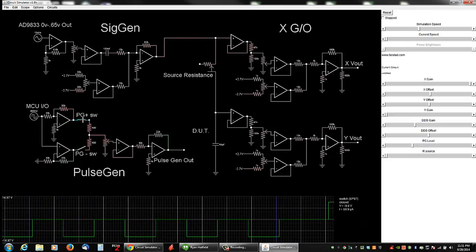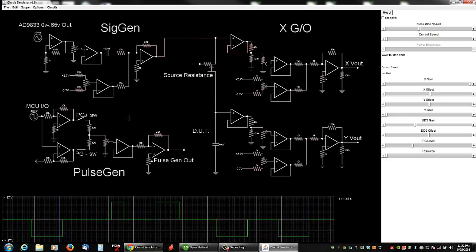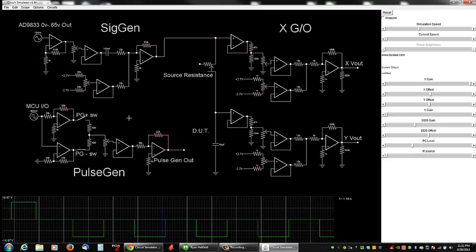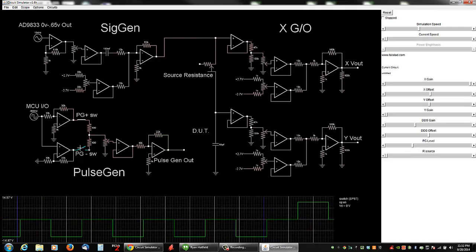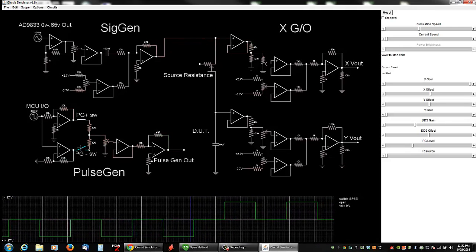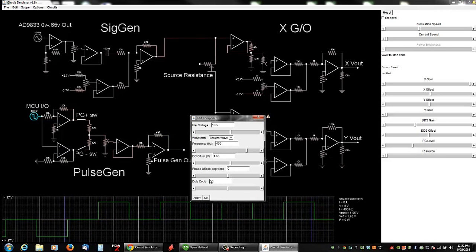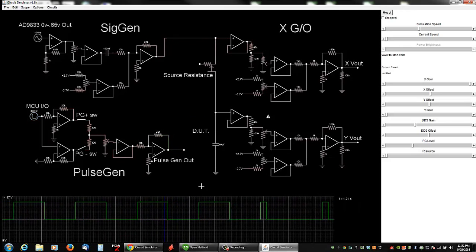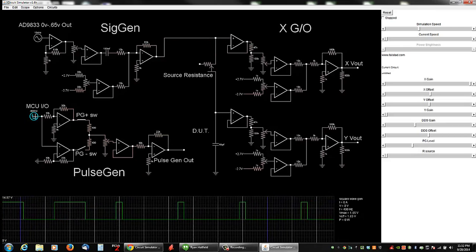And again, I shut that off, I turn that on, now it's positive, turn that off, turn that on, now it's a negative wave. And you'd use a negative wave on, like a P-channel MOSFET, PNP transistor. Use the positive wave on an N-channel MOSFET, NPN transistor, what have you. And it doesn't have to be 50% duty cycle either. Maybe it's only 10. And because that's coming off an I/O pin off the MCU, you can program whatever you want. It doesn't matter.